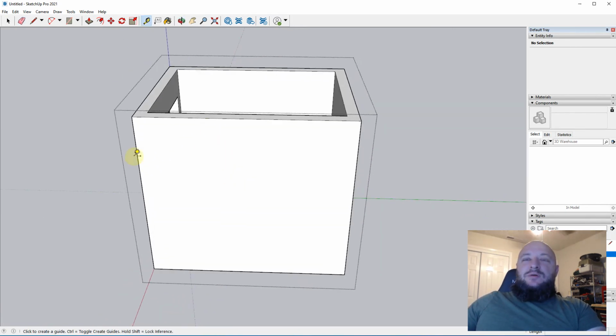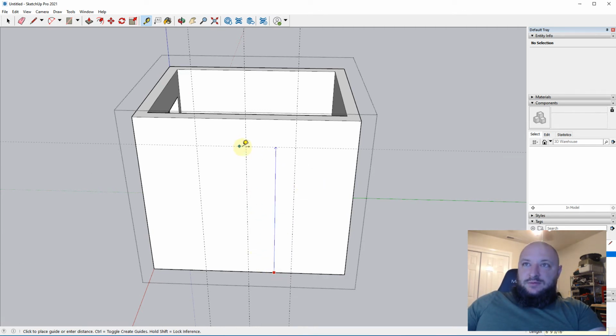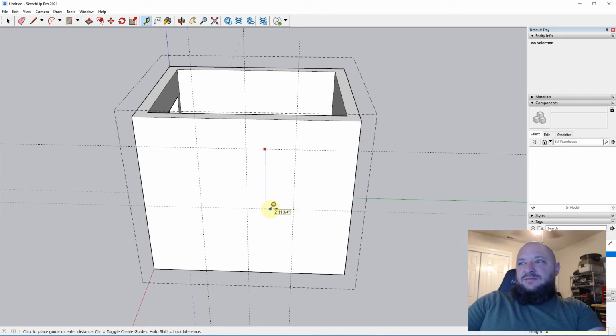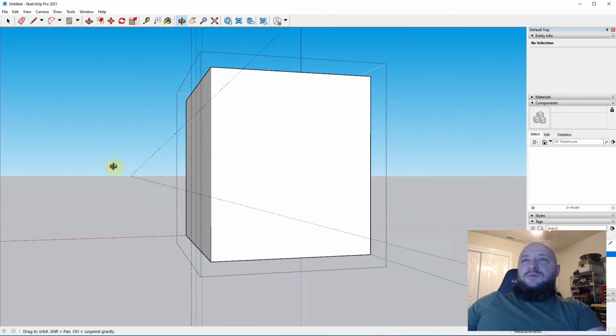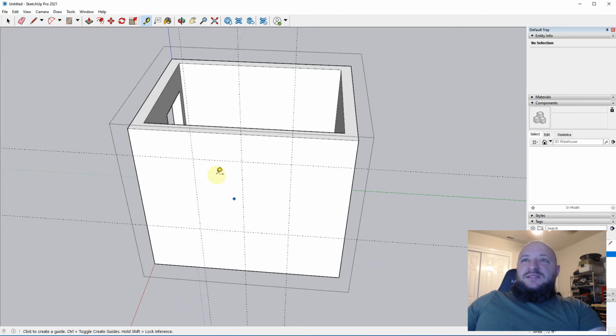And then in the center of the wall right here, we'll put a 4-foot wide window. And we're going to center this one in this wall. So I'm going to again come from the edge right here. I'm going to find the midpoint. We said 4 foot wide, so I'm going to go 2 foot off in each direction. I'm going to go up and make sure that snaps to vertical. We're going to do 6 foot 8. And we'll be crazy and do 4 foot tall, making a nice big window. Okay, so that's the space for our window.